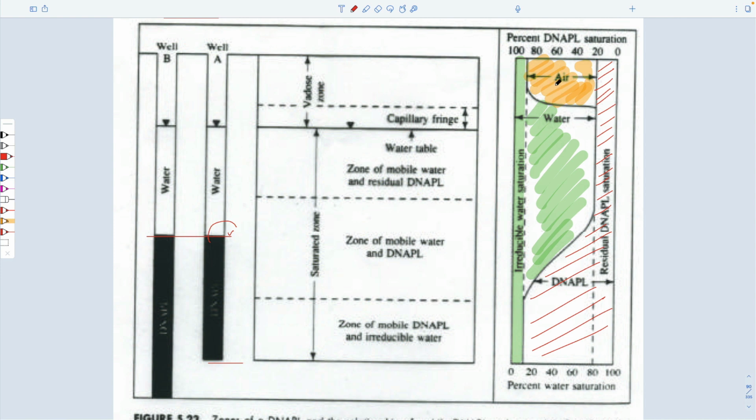Is that in the upper portion, it's mainly air-filled. It's left a smear of the NAPL as part of a chimney as it goes down. It's hit the water table, doesn't care about the water table because it's denser than water, and it keeps on going. And so it's taken this smear down through the water-saturated zone and displaced water. And then ultimately, as the capillary pressures have increased enough, as you go further down from atmospheric pressure here, the column of NAPL here competing with the column of water, the capillary pressures have been increasing, and therefore the saturation grows.